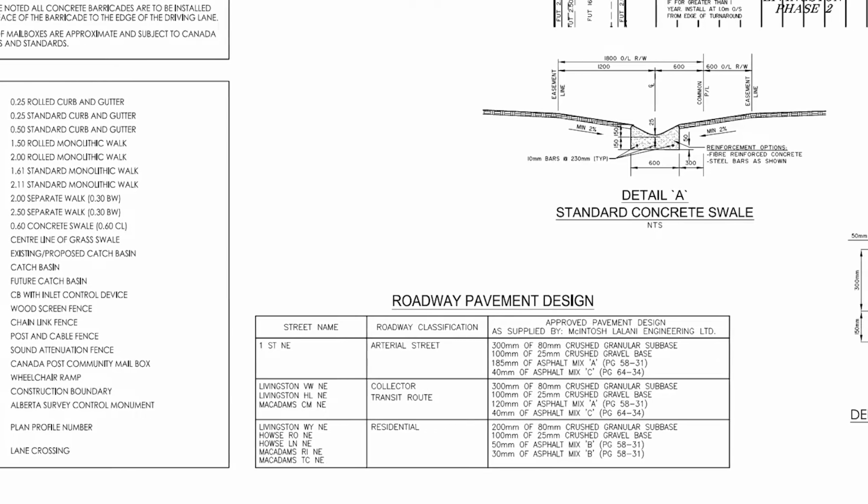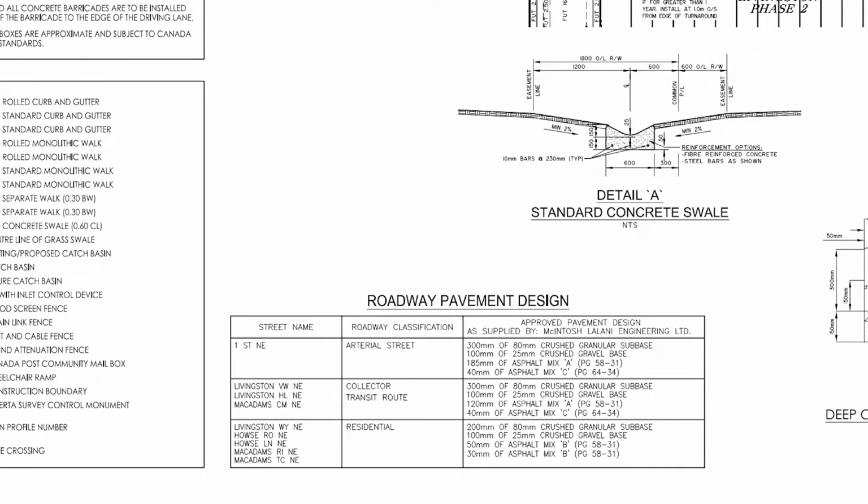The pavement design chart can sometimes be found on plans, and they detail the structure of each road. This determines the total structures of gravel and asphalt for all areas on site. Before you start construction, it is still recommended to find and double-check these numbers with your supervisor, because the engineer may change them for a variety of reasons.